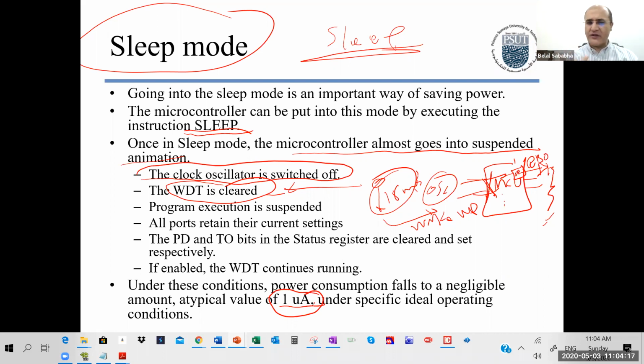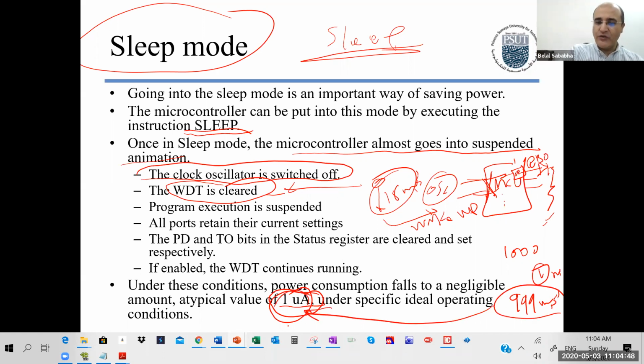How long is this battery live for? Okay, imagine if you make it sleep and wake up every, I don't know, a few seconds, 1 second, okay? Do something for like 1 millisecond, then in 1,000 milliseconds, you're only doing something 1 millisecond work, then you are saving 999 milliseconds doing nothing and dropping down the power consumption to the minimal.